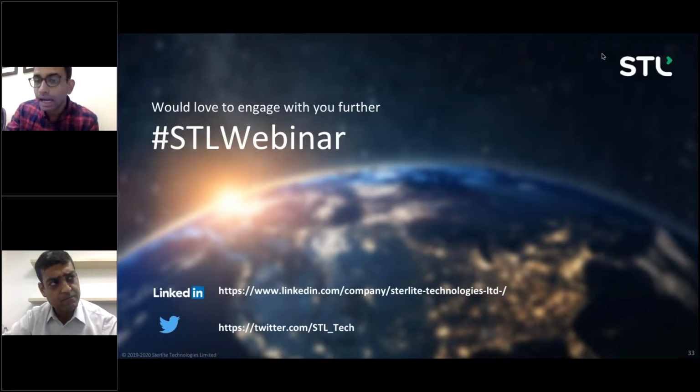in bits and pieces? Yeah, a great question, and that's exactly the problem we think we have answered with Stellar. So what we have at Stellar is a G.657A2 fiber. It has the mode field diameter of G.652D. So you're right. That mismatch in MFD is one of the critical elements that operators and installers face difficulty with every day. And with Stellar, we have designed a fiber specially to address this particular issue.